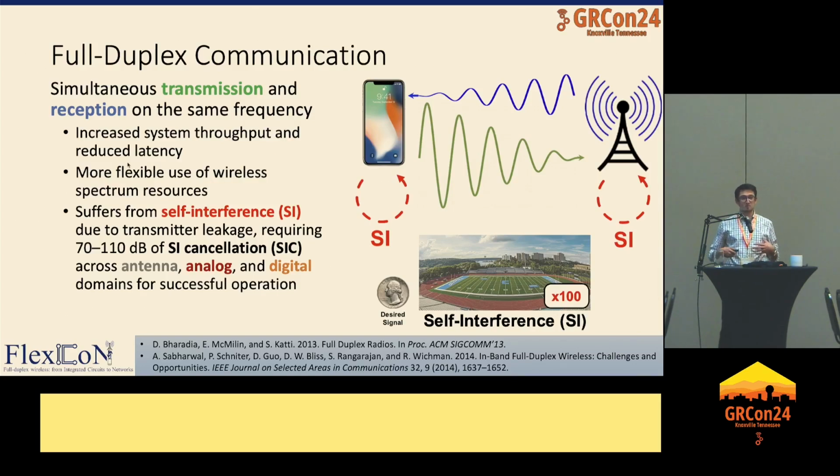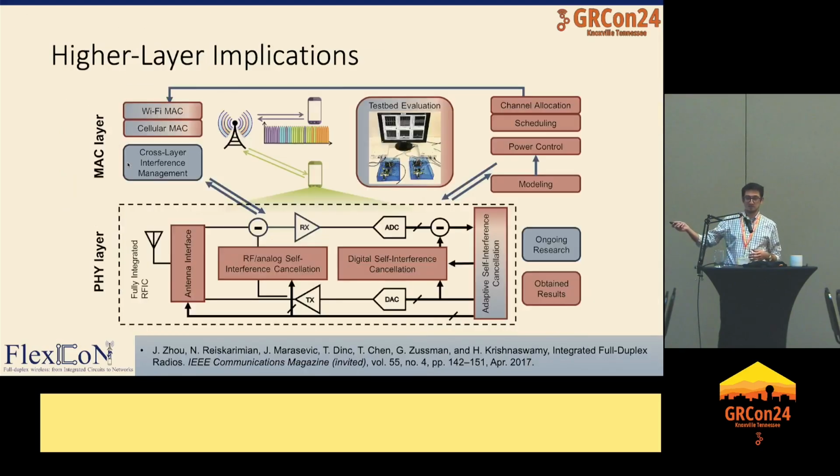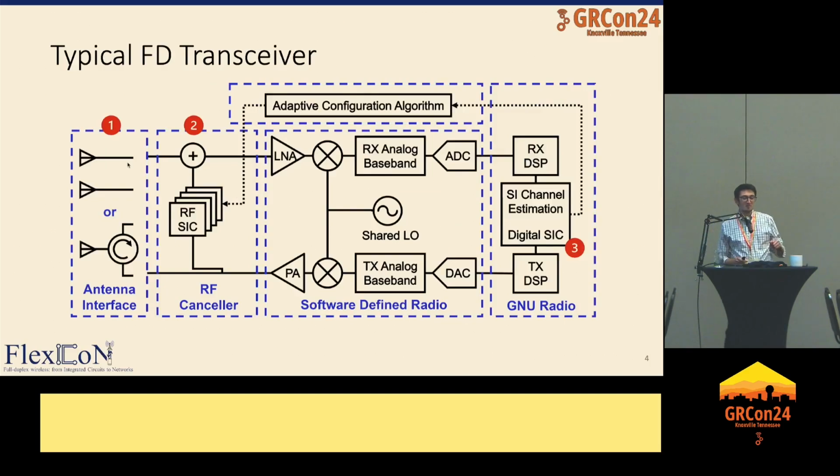So what we do is you really just throw the whole toolbox at it, right? Spoke about this already. Essentially, you have 3 levels of self-interference cancellation that you could apply in your typical full duplex transceiver. First, you have your passive RF isolation, which is your antenna interface, whether you have a single antenna scheme, such as a circulator or an EBD, or you have a dual antenna scheme where you literally use the physical distance between the two for your isolation. That serves as the first step.